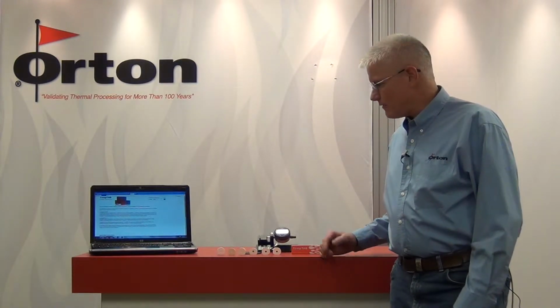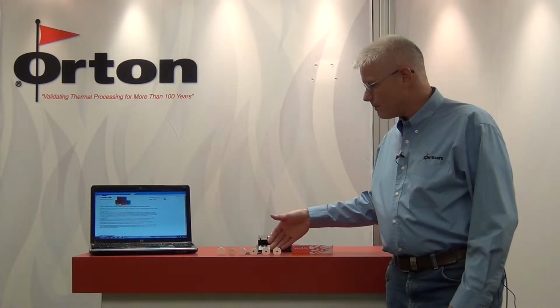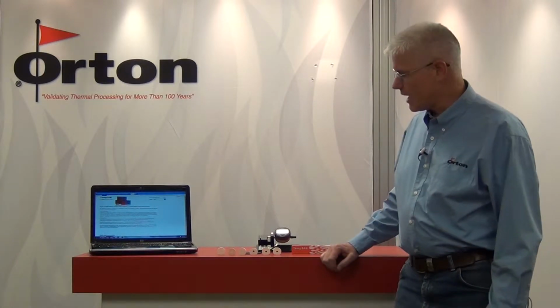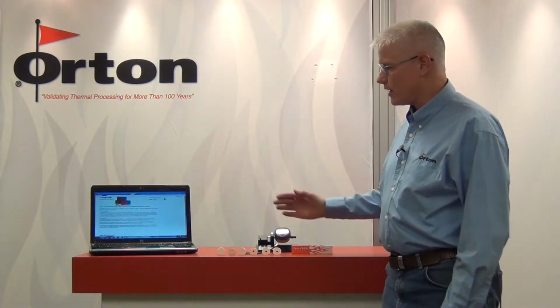Our TempTAB product was developed for use within vacuum furnaces and furnaces used to process metals in atmosphere and the absence of atmospheres. We have different versions of the TempTAB that are designed so that when they go through your process, they shrink. And you measure that shrinkage, and you can change that to a temperature based on some data that we have compiled within our software or into a paper chart.